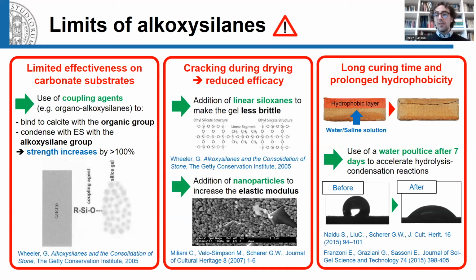To overcome this problem, strategies have been proposed, such as the application of poultices of water or water-ethanol solutions to accelerate the hydrolysis of the consolidants, so that the hydrophobicity can be lost in a matter of days instead of months.